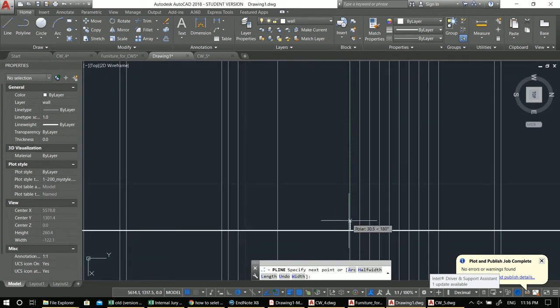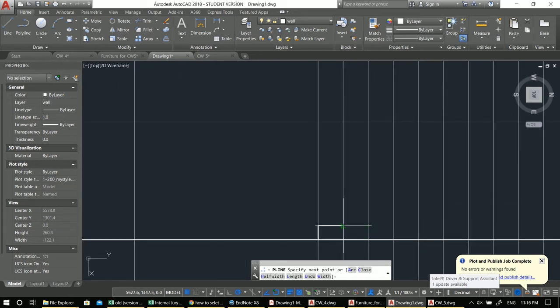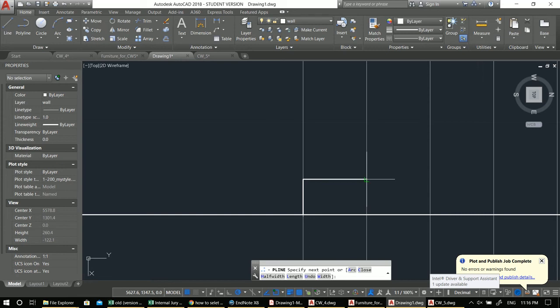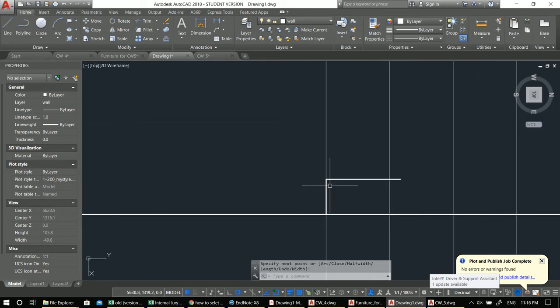So it comes up 17 centimeters and goes here. But be careful, because it will not stay here, because we have 5 centimeter nose of the stair. So it will go more than that. So I'm clicking here, I go 5 more. And this is it. And now I have to put the nose here. Let's say PL again, 5, 5, 5. Let's go ahead and trim this.